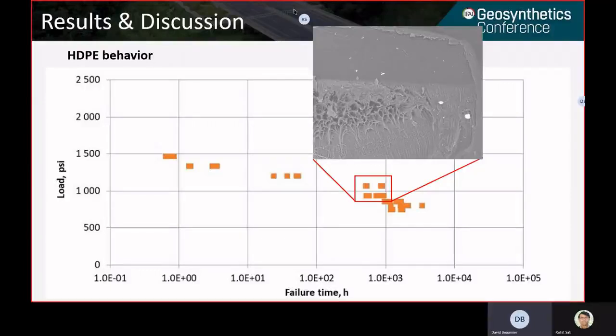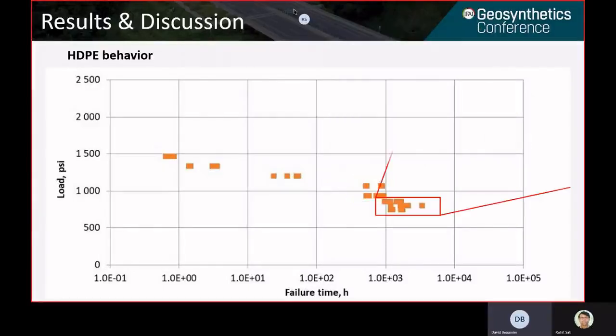And this is how this stress cracking is first initiated. After a certain time, where it hasn't propagated to a certain point, it gets back on the bottom of the image to a ductile mode of failure at the end. But all this is basically initiated from stress cracking, a brittle type of stress cracking.